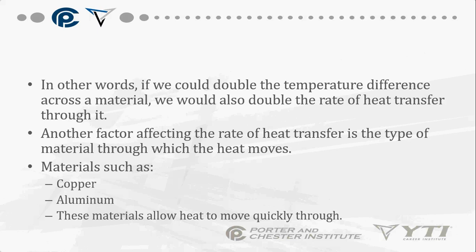When you look at your baseboard, you will see that you have a copper pipe getting shoved through a bunch of aluminum fins. The way that baseboard is operating is I am delivering hot water through that copper pipe that's going through the center, where the aluminum is now acting as my heat transfer medium. That aluminum is what's giving off the heat to the space. It's not the copper. The copper is nothing more than just the conveyor belt that's just delivering the water to the aluminum. The aluminum is what's doing all the work.